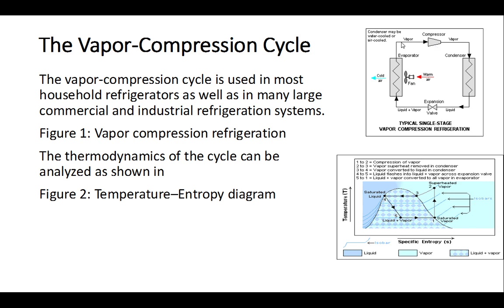So we've got the vapor coming into the compressor. And again, remember when we turn vapor into liquid, we lose energy. So that's the reason why we get heat released from this process. So the vapor is pressurized, and as the vapor pressurizes, it goes through the condenser. The condenser in turn will lose a lot of heat, and so we release the calories, the energy of the refrigerant, through this condenser, and it slowly turns into a liquid.